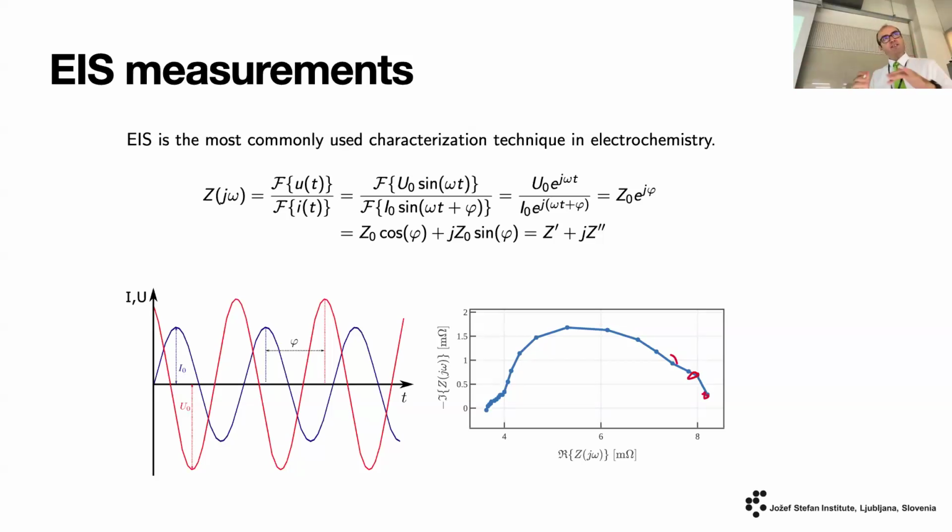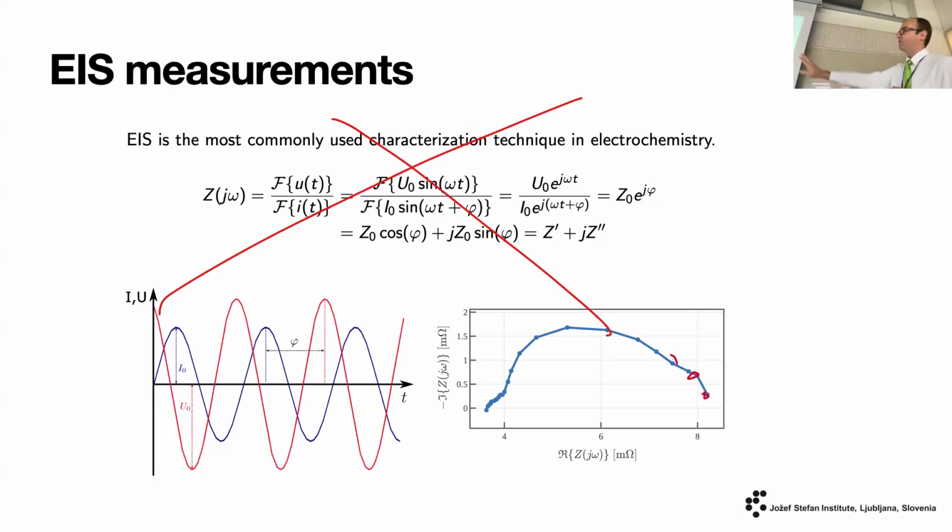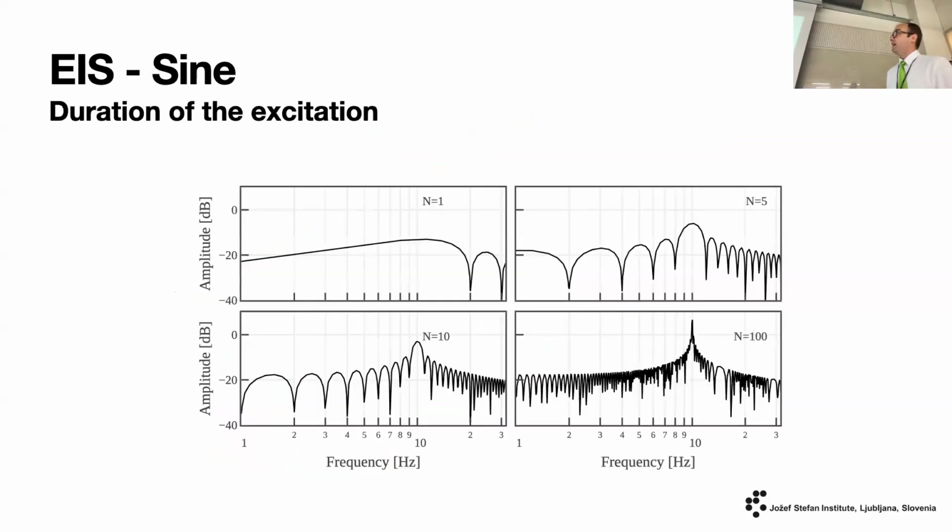So I have to say, this is quite explainable. No one does it like this. Even if you buy Zahner equipment or BioLogic that does only sine waves, I'm going to show you tomorrow how they do it properly because of noise issues. But if we have a noiseless scenario, this works, and this is quite nice. So the one thing that we have to keep in mind is the duration of the excitation is important.